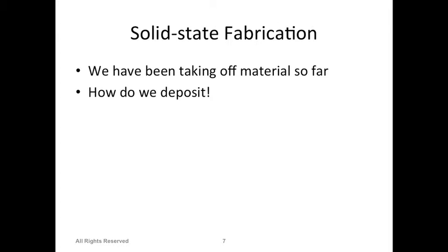So we do need to actually deposit material. If you remember, have you seen any of you the glucose meter strips? The glucose meter strips, which are used to measure sugar level of glucose in plasma. Have you seen that? In the strips, you might have seen there are electrodes on the surface, right? Very small electrodes. So we can actually use photolithography to make those electrodes, many of them.